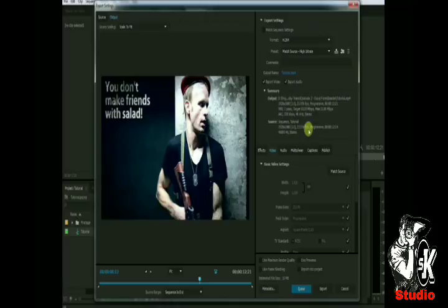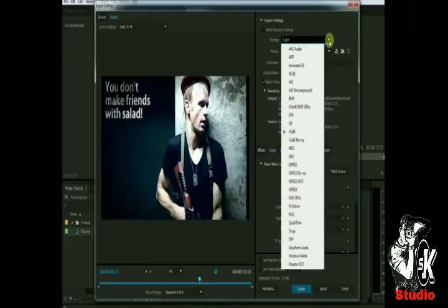to export. Over on the right-hand side, you will find a large number of export settings, and yes, things can get a little bit confusing. In my opinion, however, there are only a few settings that you really need to care about. The first one is the format. This option defines the format of your output file. For example, it may be an AVI, it may be an MOV, an MP4, a GIF sequence, or any other form of output. For my exports, I usually prefer to select the H.264 option.